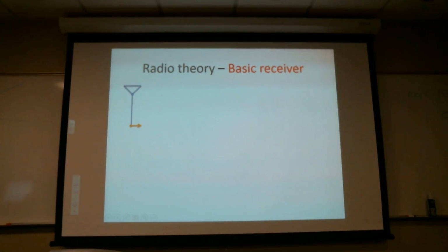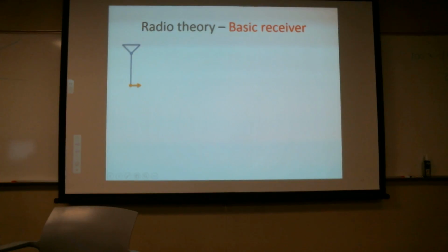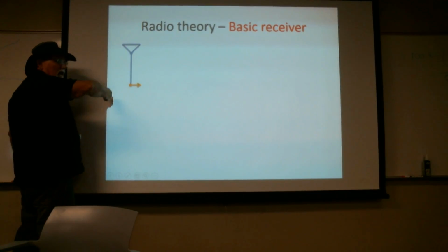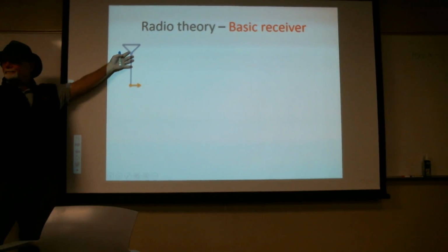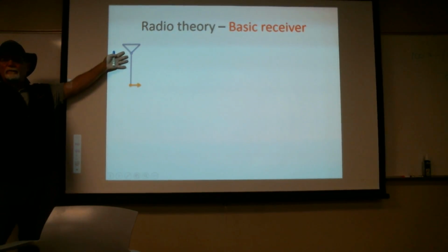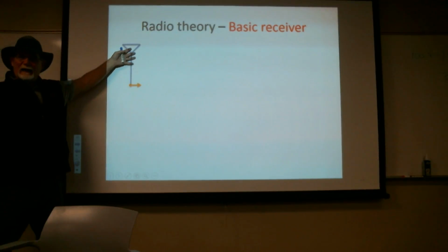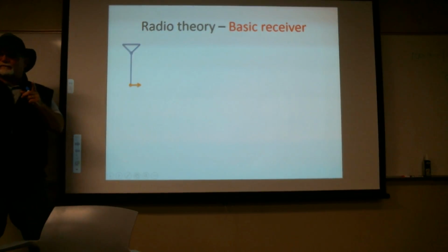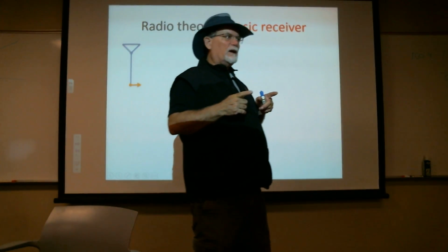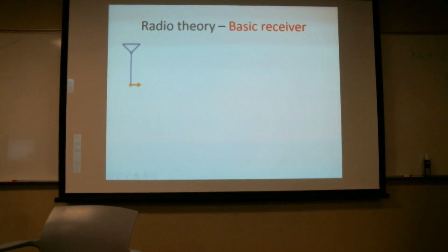Then the reverse is going to be antenna, electromagnetic radiation causing electricity to go back and forth in the line in whatever waveform. And the truth is, there's all kinds of different frequencies being picked up by this, right? However, higher and lower frequencies aren't going to move the electrons too much. Just those frequencies that are the right length for the length of the antenna are going to create the most action. So the value of having a narrow band of sensitivity for the antenna is that its physical length filters out all the rest of this unwanted noise.